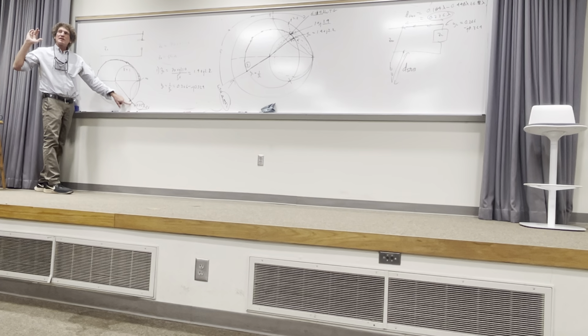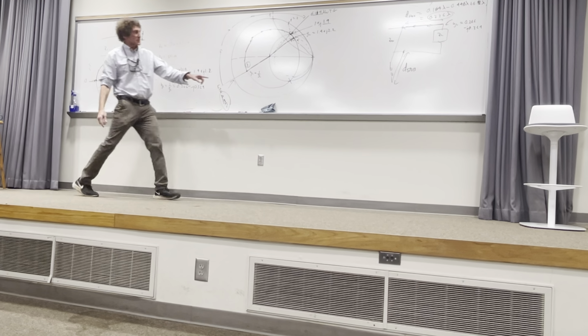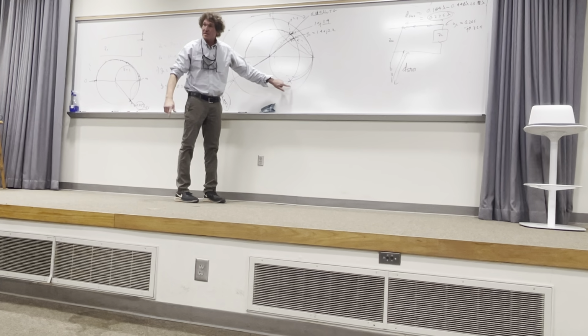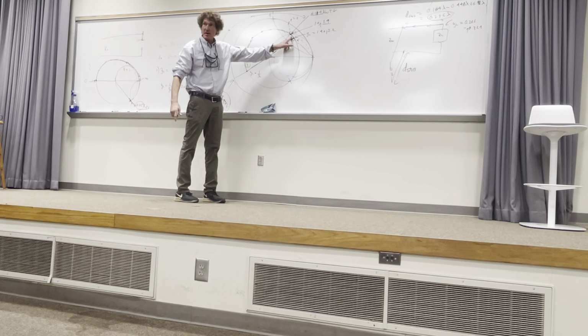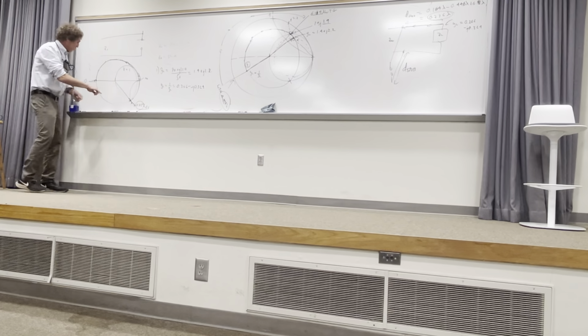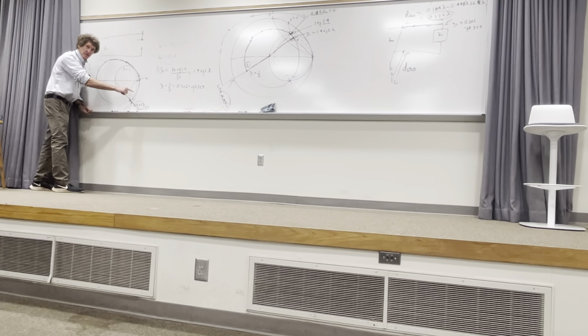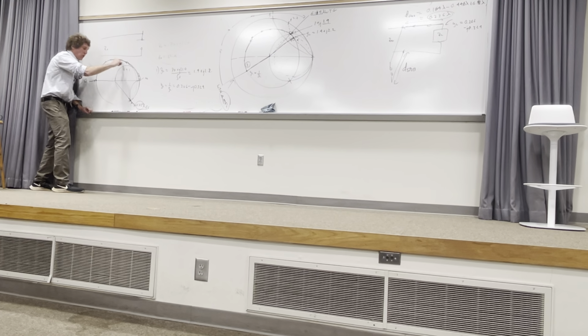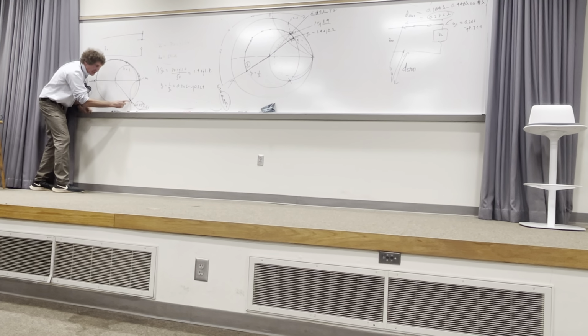Hold on, class, hear me, all right? I don't care about this point right here at all. We're not talking about this, we're going to use that point, aren't we? That's where we're landing, that's the short distance, please hear me. Now, go over here, this is a different Smith chart. I'm only going to be moving on the rim here. This has to do with the stub, everybody got me? Now, please, everybody take a look, if you go all the way around here, where J 1.9 is here, shoot a line straight through here, what do you read there?